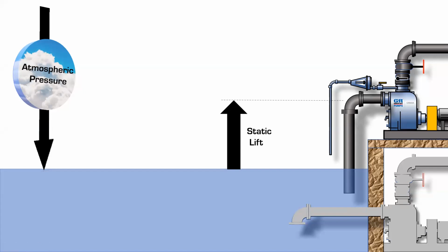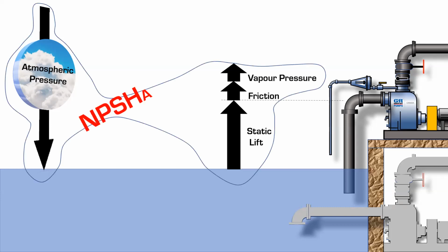And that vacuum is a partial vacuum. We had to do that. So that's going to be a negative. That's going to be acting on that liquid as it enters the flange, the suction flange of the pump. As always, we have to take away the friction and then the vapor pressure. And then once we have that, we have NPSH. Again, this is the pressure of the liquid, absolute pressure, just as it enters the suction flange, including the vapor pressure. And finally, NPSHR, just from the manufacturer, it's going to change with flow, safety margin.